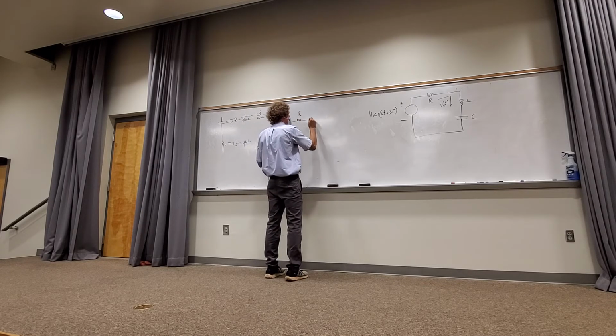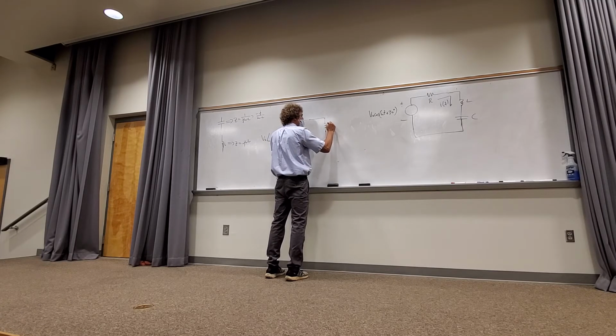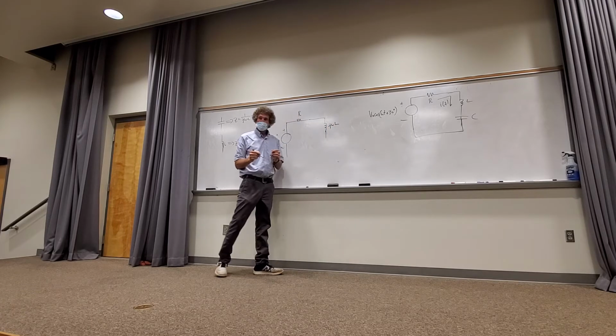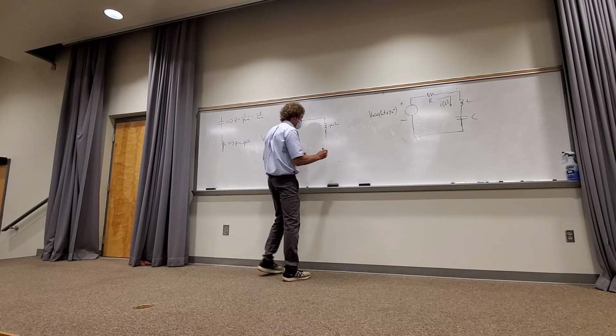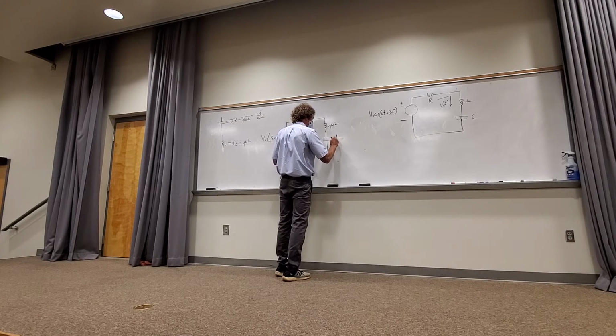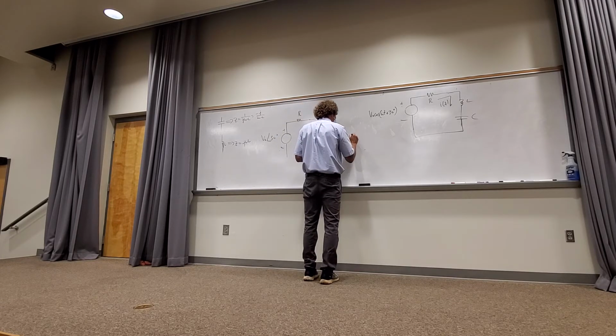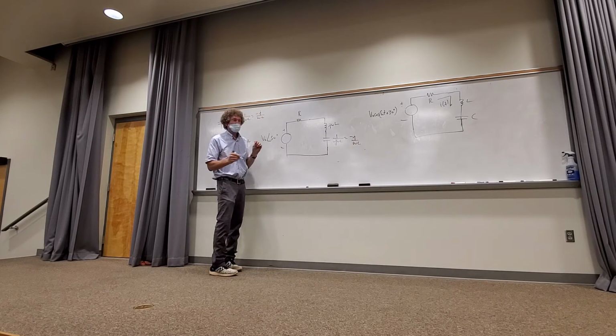Over here, now there's an inductor. We replace the inductor with its impedance, or its inductive reactance, j omega L. All right? It's just like resistance in terms of what we're going to do with it. Then there's a capacitance. And the capacitor here has an impedance of 1 over j omega C, or minus j over omega C. And then you have this. Now this is in the phasor domain.